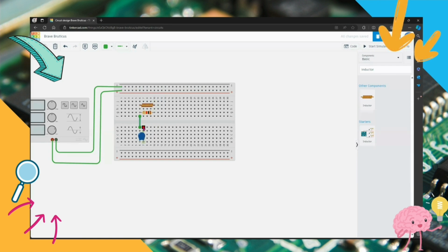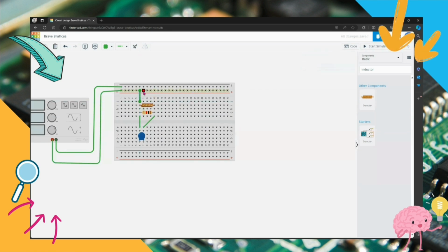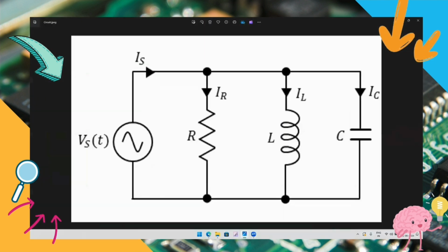Now we are going to connect the supply. For connecting the supply with the pins in our breadboard, we are going to connect the parallelly connected nodes of the RLC circuit in a way that one is connected to the positive terminal. So for that I am just going to short these two pins, and for the negative connection I am just going to short the other pins. We will be connecting the positive terminal first. I think with the positive it would be easy for you to understand. It's a simple connection. Just apply the basics of the breadboard as I have already discussed with you.